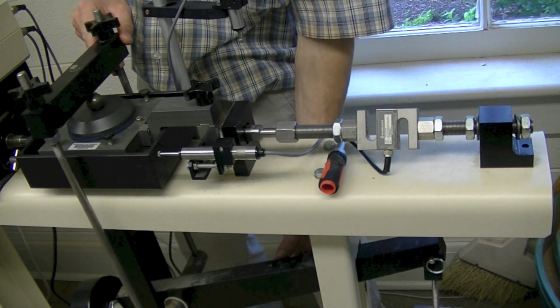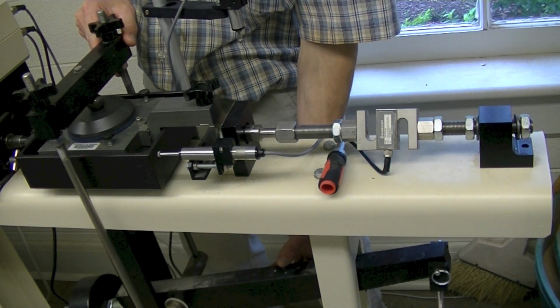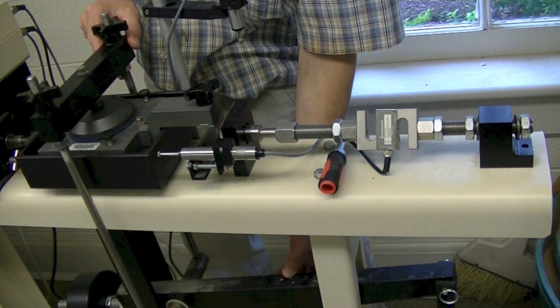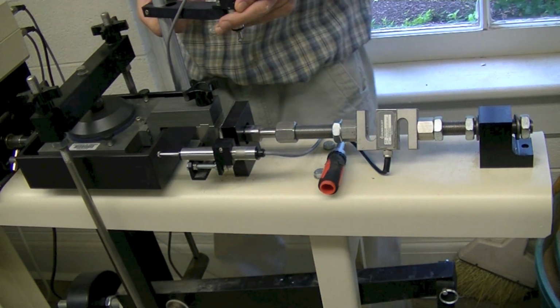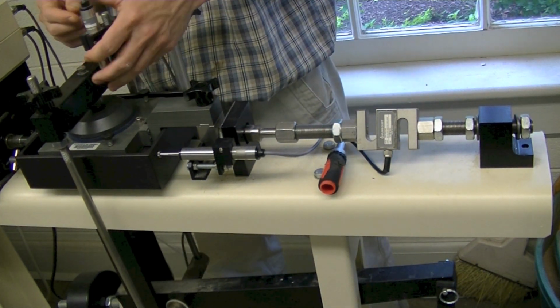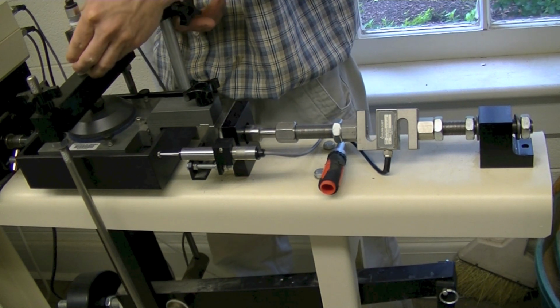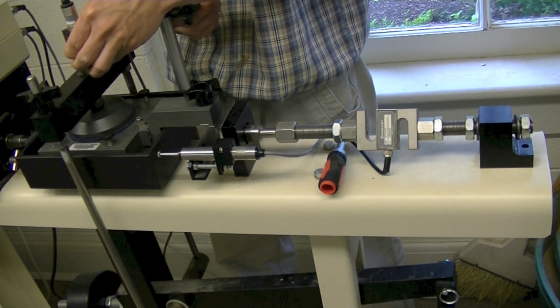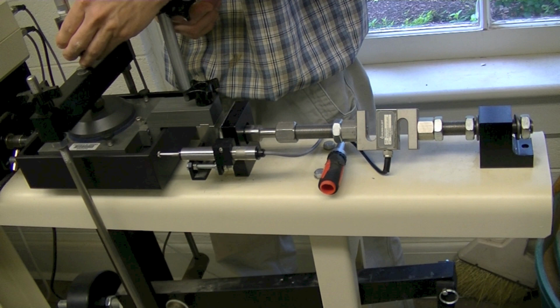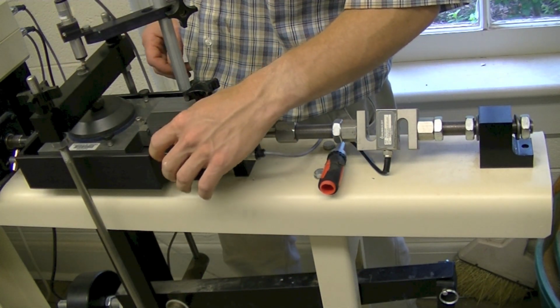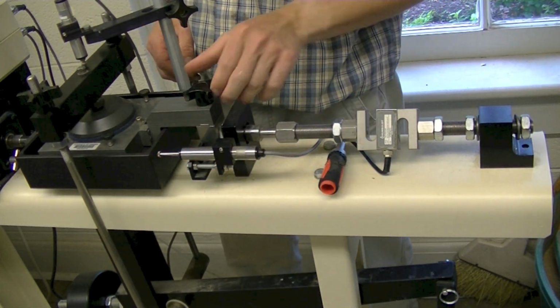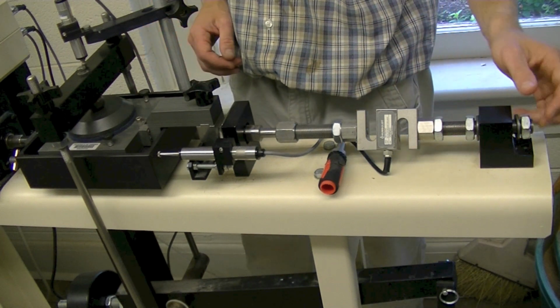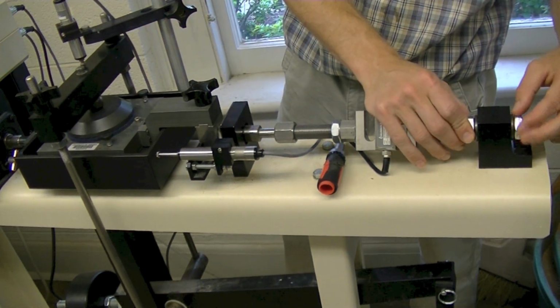Swing the vertical load beam assembly to rest on the ball. Adjust the carriage to rest evenly on the ball by using the nuts beneath and wing nuts on either side of the beam if necessary. Swing the vertical LVDT over so that the tip rests on the beam. Also ensure that the horizontal LVDT tip is touching the side of the box to measure horizontal deformations.